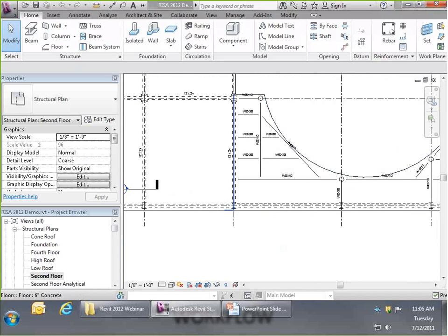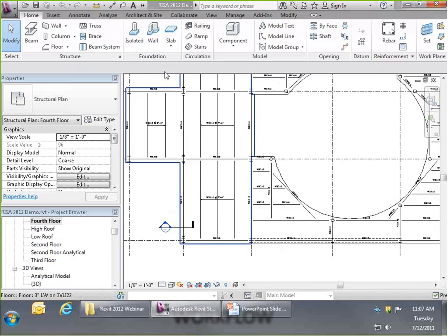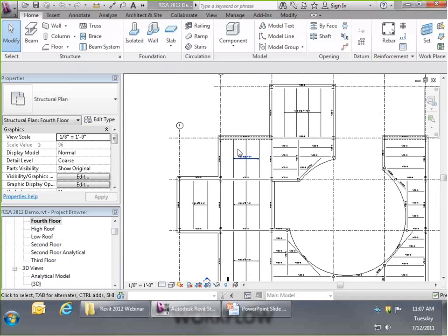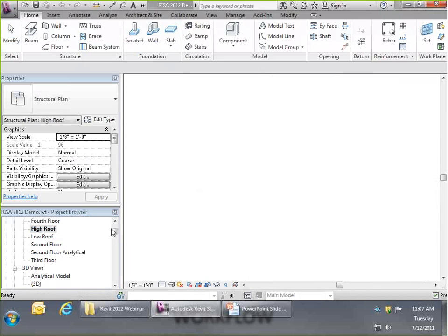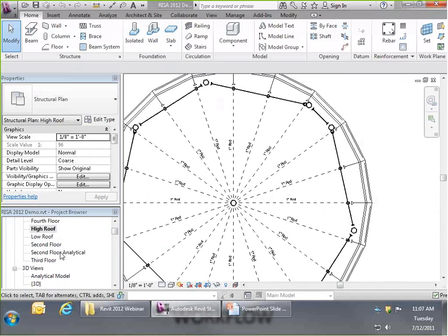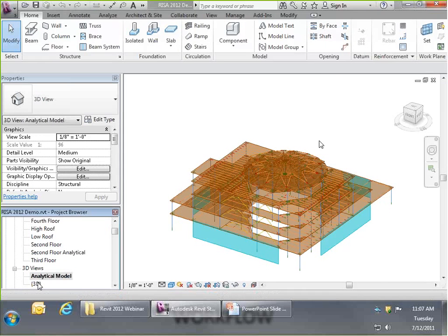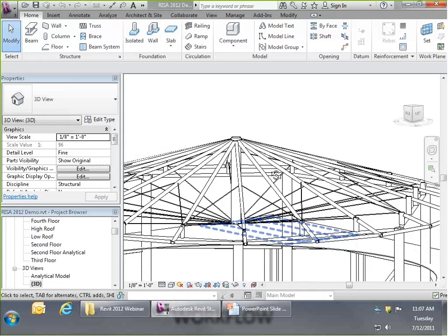Now, on top of that, I also have some walls as well. These are going to be concrete shear walls set up. And on the upper floors, say the fourth floor, here we're looking at all steel, and this is intended to be composite steel. And then lastly, once we get up to the roof, we have this dome situation set up with a truss using these hanger rods as the tension members in the truss.